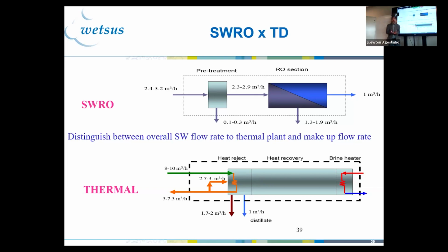This is a closed cycle that you need to keep for the cooling water. You know, that you can simply re-inject. So in fact, you should not see this. You should see 10 minus 7 liters of cooling gives you how much? 3. From these 3, you get 1, which is, again, 33%, right? So one should not mix the cooling water fraction in the thermal desalination system with the production factor.